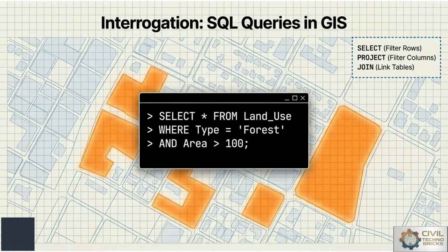With respect to those queries, the geographical information system updates the existing data based on the data in terms of rows, columns, keys, links, or any relation. So structured query language interrogations are used in GIS to retrieve, filter, and analyze the spatial and attribute data efficiently for engineering applications.